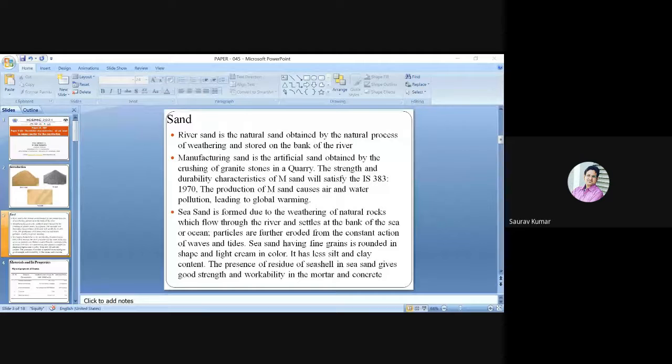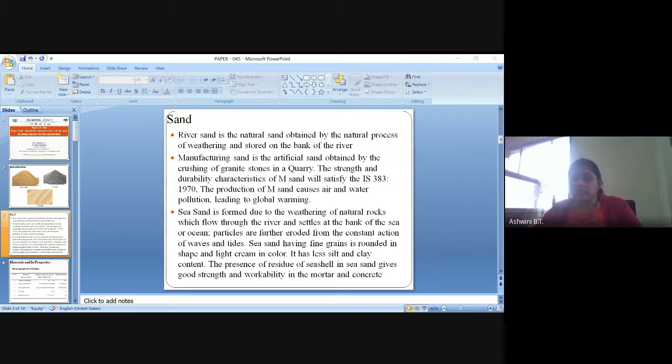Yes, sorry. These are the material properties of the cement. As we have done cement mortar, we tested the cement as per the standard IS 4031. We did normal consistency, initial setting time, final setting time, fineness, and specific gravity. These are the obtained values of the experiment. The normal consistency range is 26 to 34%, and we got 32%.